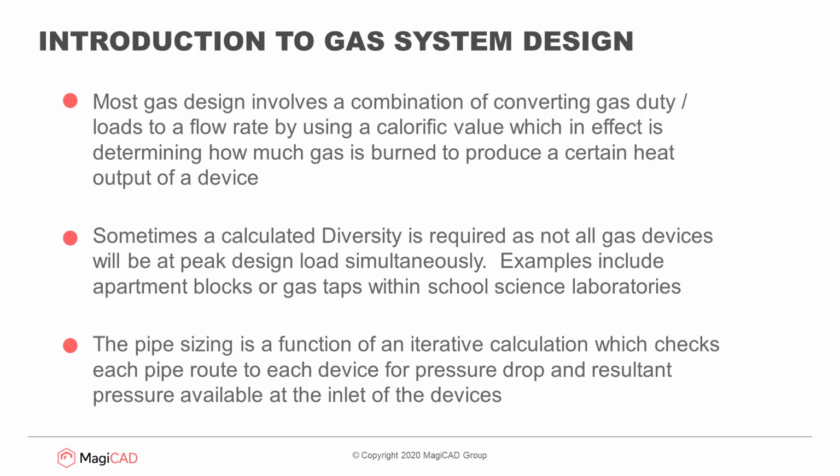Most gas design involves converting the duty of the loads to a flow rate by virtue of a calorific value, which basically determines how much gas is burnt to produce a certain heat output at any device. That's the underpinning factor in the calculations itself.